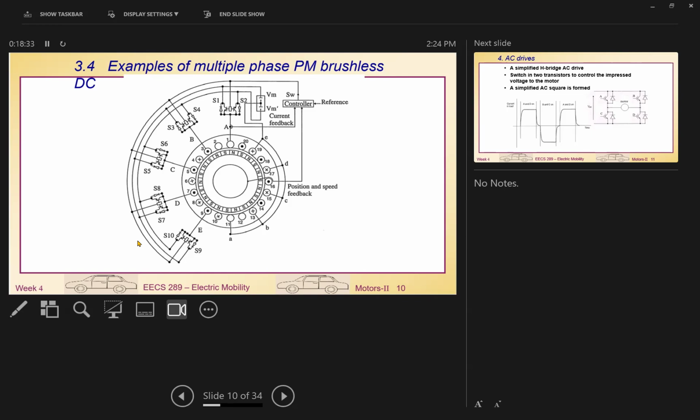The motor is more rotating. It won't suddenly stop. So when the motor rotates away from this broken phase, it can still continue the operation. So that's why we tend to use multiple phases. That would be more advantageous. So that's how a real multi-phase brushless DC motor looks.